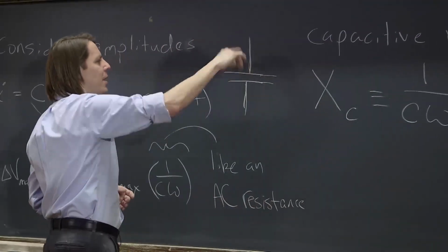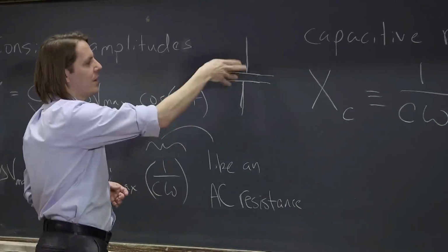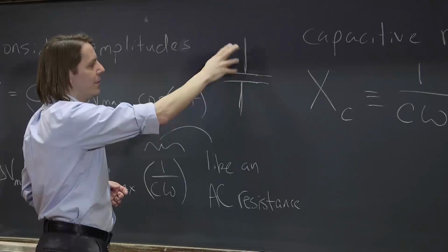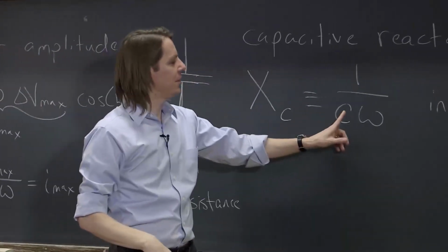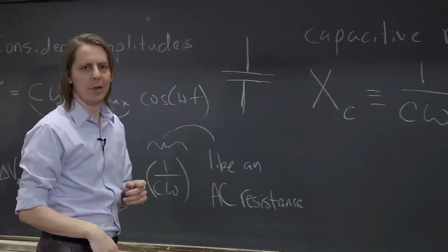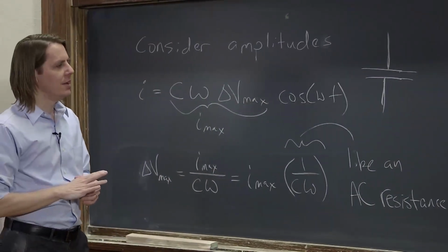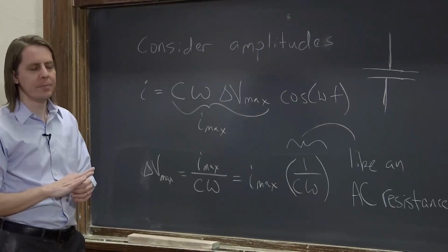When you have the frequency really high, it's constantly charging and discharging, charging and discharging. So it's like it's not even there. Right? So all the very fast charging, discharging, basically then the frequency is very high, the capacitive reactance is very small. So that's what's unique about capacitors, and in a minute you'll see about inductors, is that their behavior in the circuit depends on the frequency.